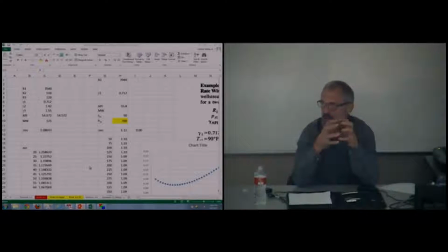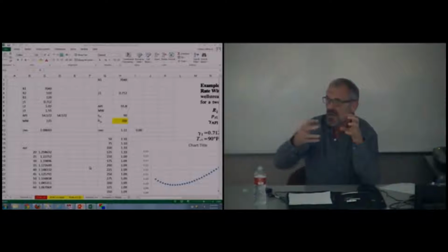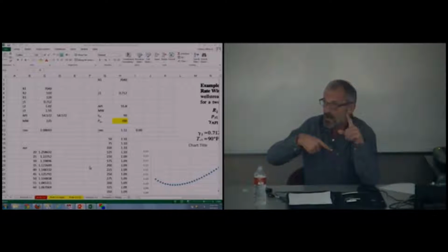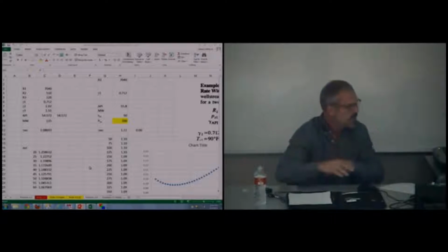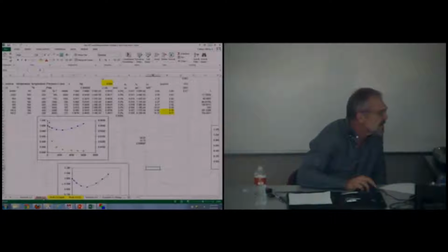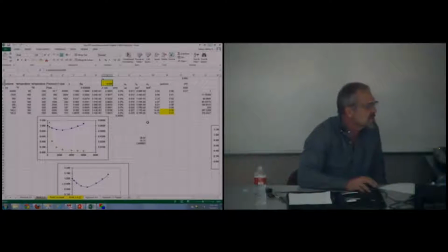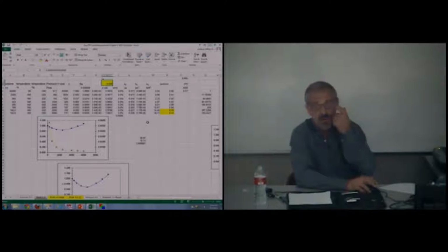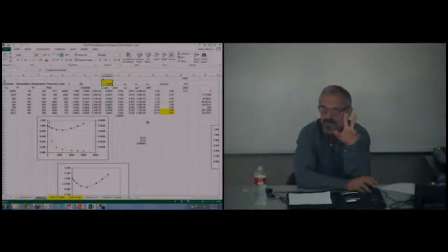It's the one where we did the piston, calculated the Z factors. We modeled the gas gravity to fit that data and calculate the gas gravity. Wasn't that problem 1.3? Yeah. So what did we? Yeah, we calculated using goal seek or solver. You remember? I realize this was 2 weeks ago, so maybe you don't remember.